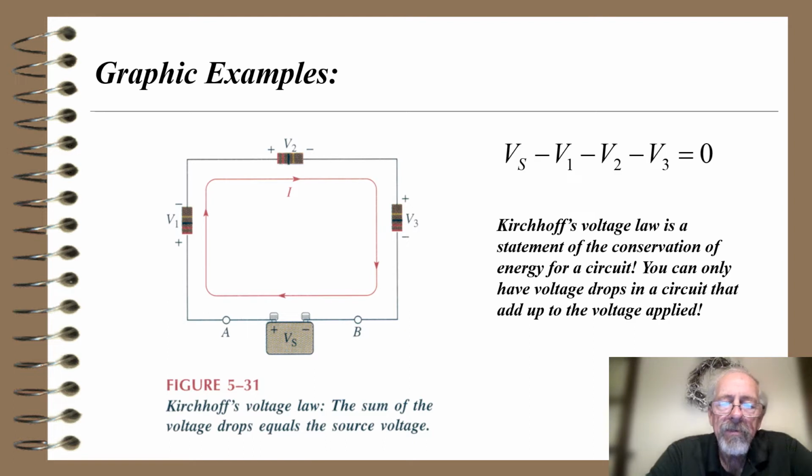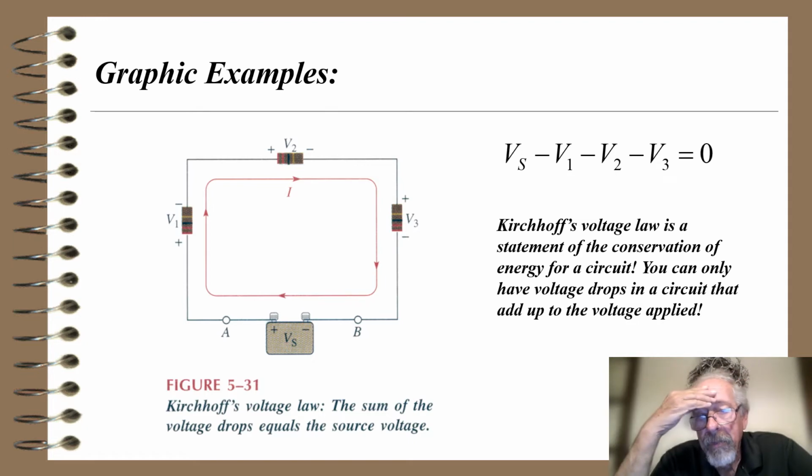So again, Kirchhoff's voltage law is the sum of the voltage drops equal the source voltage. And basically it's nothing more than a statement of the conservation of energy for a circuit. You can only have voltage drops in a circuit that add up to the voltage applied.